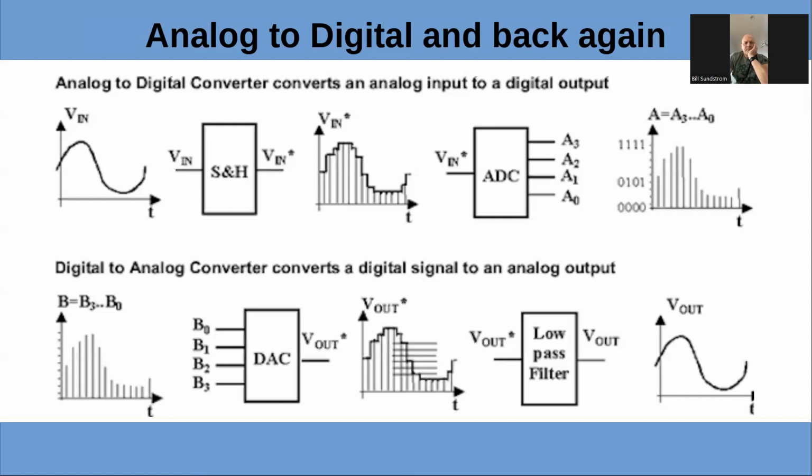You can actually make filters that you can't build in the real world. You can make almost like a brick wall filter where the skirts are essentially vertical. All kinds of transforms and easy to do single sideband using the Hilbert transform, which is on the extra exam.